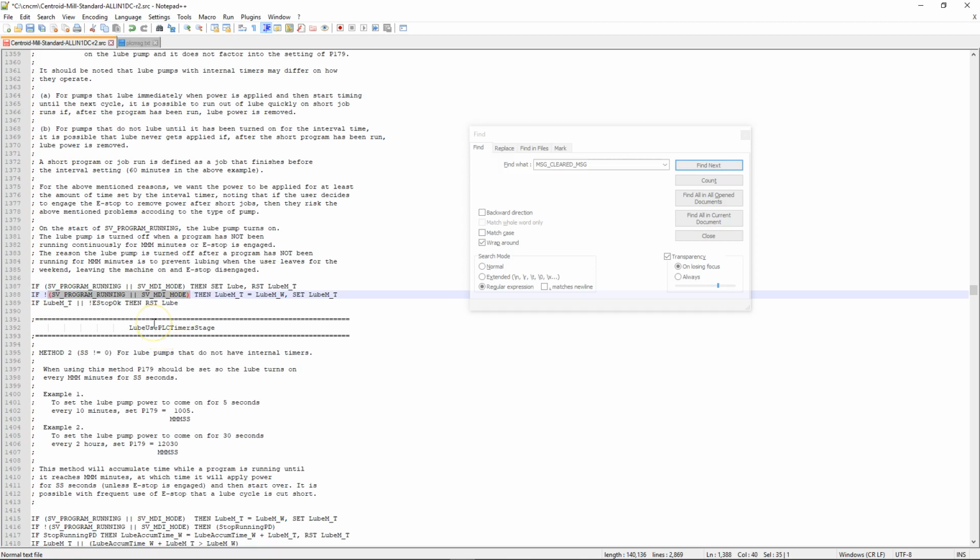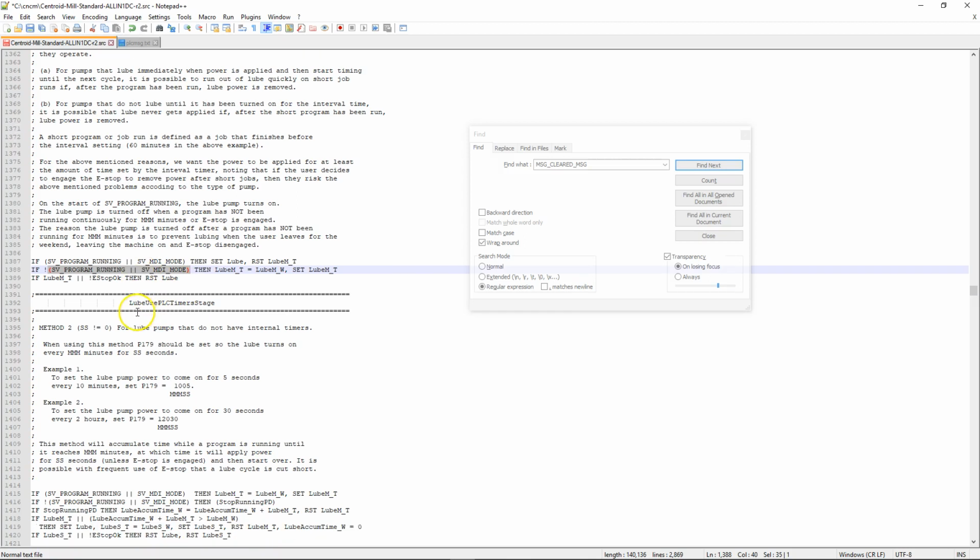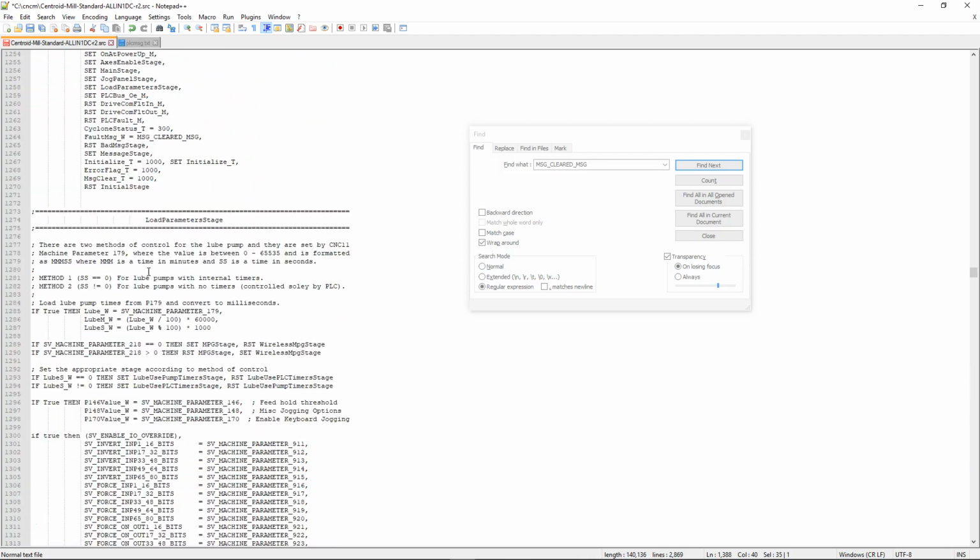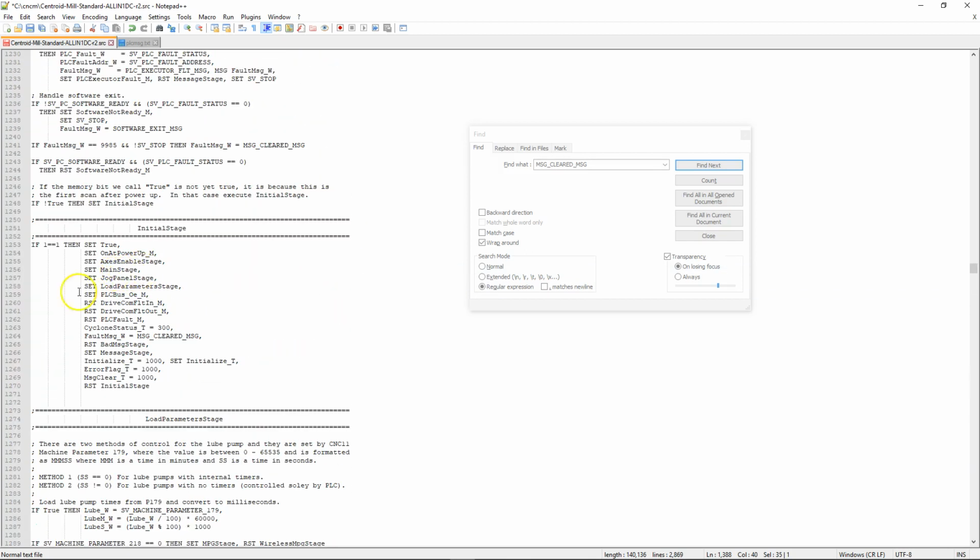All right. Now, I'm just saying that because you'll end up seeing a lot more logic down below that might have multiple different types of conditions, and you need to make sure that the appropriate condition is in the parentheses, because if not, you may end up getting lost, and certain things won't be turning on because there's a missing or an extra parenthesis that shouldn't be there, which makes that condition no longer true when it really should be true.